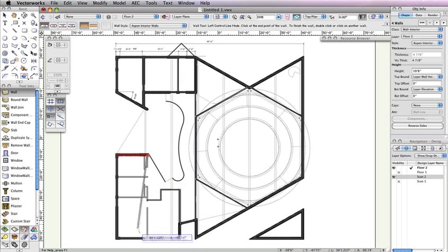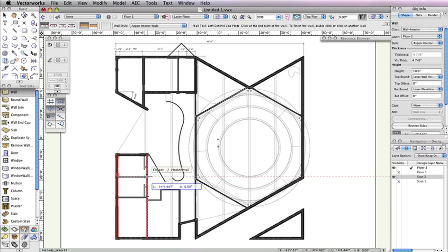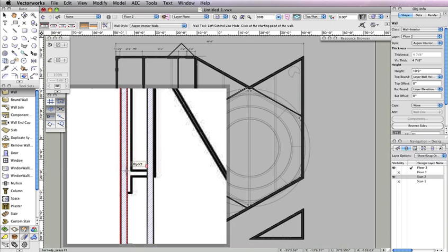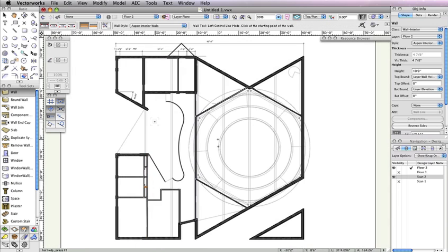As you're tracing the walls, press the U key to cycle through the wall alignment modes in the toolbar to make tracing easier. Additionally, don't forget to use the Snap Loop to get a closer view when necessary. Here's what you should have once you're done.